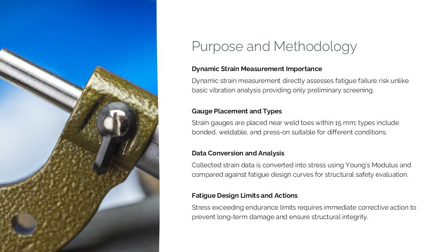Bonded gauges require surface preparation and are time-consuming. Weldable gauges are suitable for high-temperature environments, and press-on gauges offer rapid deployment for operational assessments. The strain data collected can be converted into stress values using Young's modulus, assuming uniaxial conditions, which is reasonable for most fatigue modes involving bending.